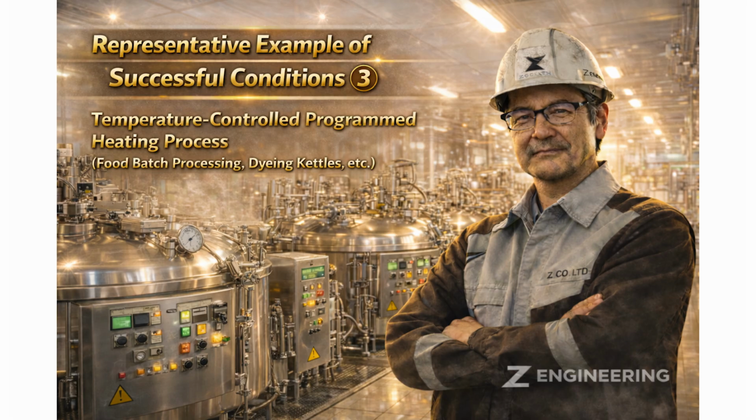Now let us look at a case that appears unstable at first glance, but in fact can still work. Processes controlled by temperature programs. For example, batch heating processes in food factories or dyeing vessels in textile plants. These processes follow programmed temperature steps. Heating, holding, cooling, all temperature changes are controlled by a program. Steam consumption is automatically adjusted according to that program.